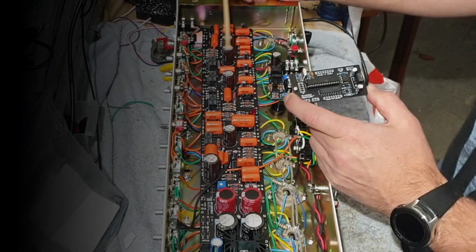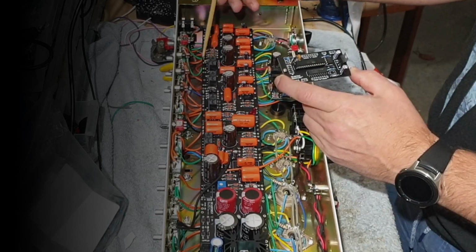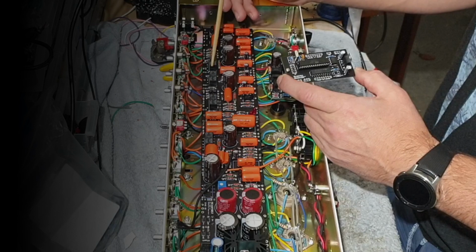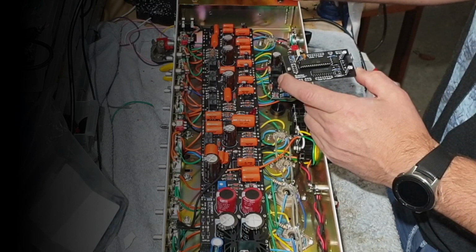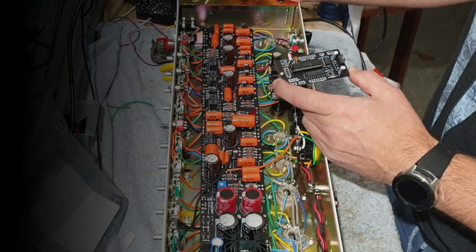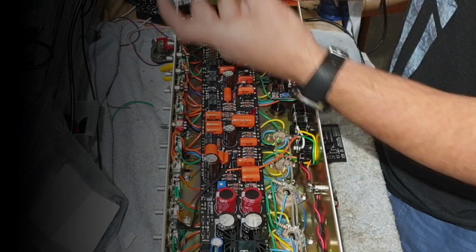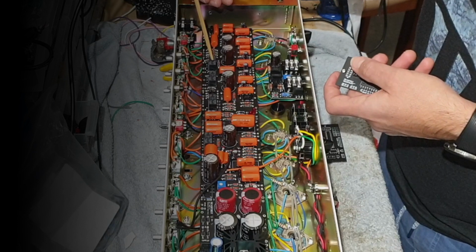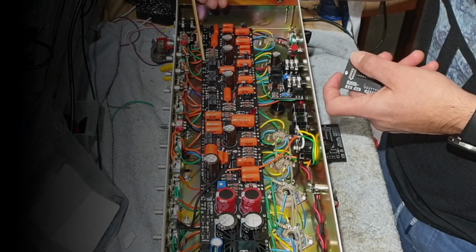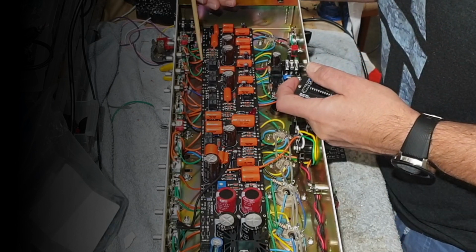I've done lots of builds with 5-volt relays because of what the power transformer had as an option. If you're doing that, you can just run your 5-volt supply for the MIDI board straight off one of the VCC pads that I have on the board.